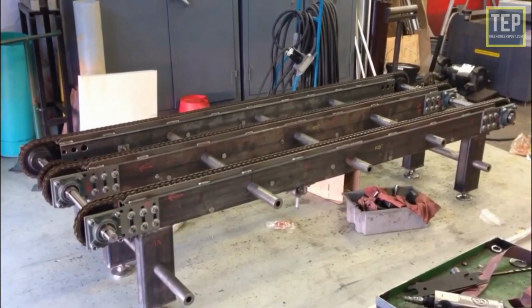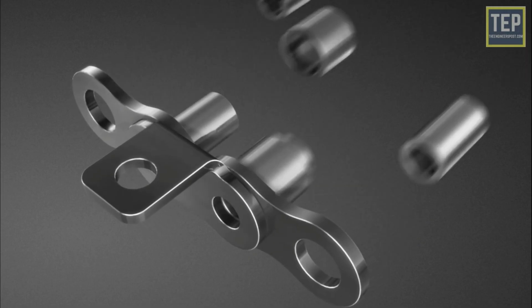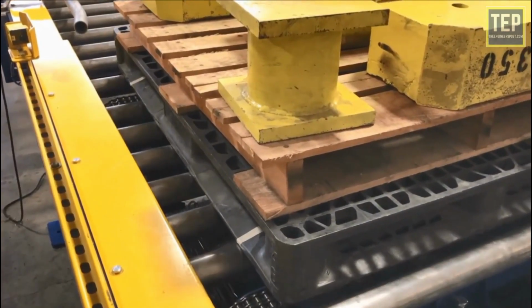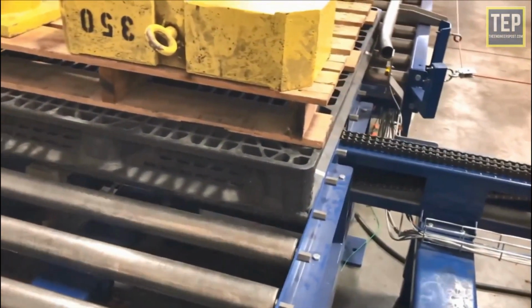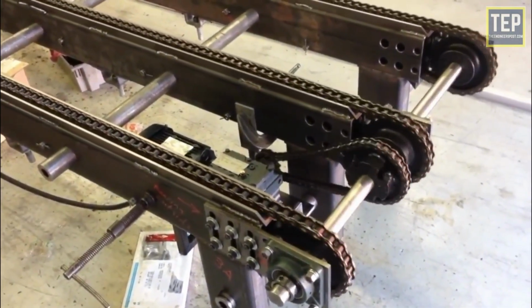A conveyor chain is a chain that has been specially developed for chain conveyor systems. It consists of a series of plain bearings that are held together by connecting plates. Each bearing consists of a pin and a bushing on which the chain roller rotates. It is used to move the materials from one place to another. This type of chain is well shaped so that it can easily run over the sprocket. The one major disadvantage of this type of chain is that the motion of the chain is not smooth, and also there are chances of wear and tear.